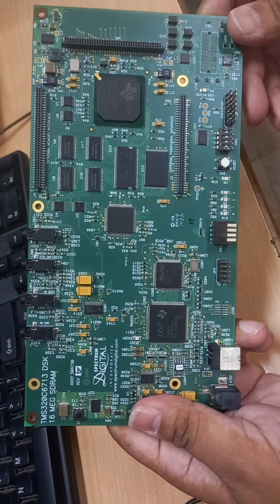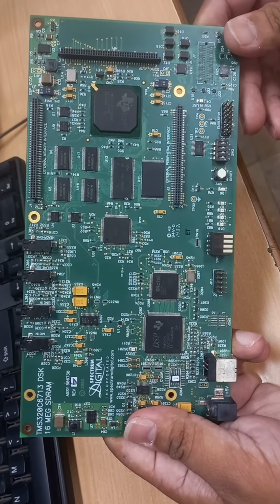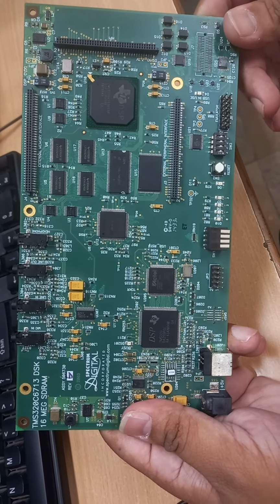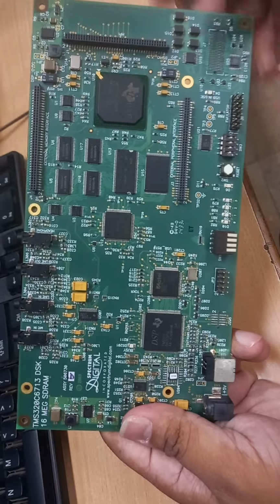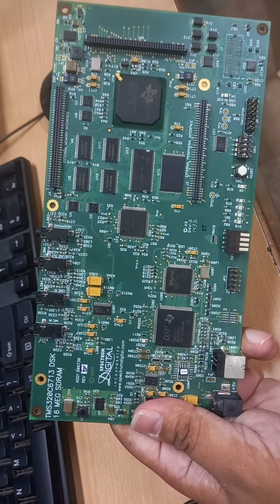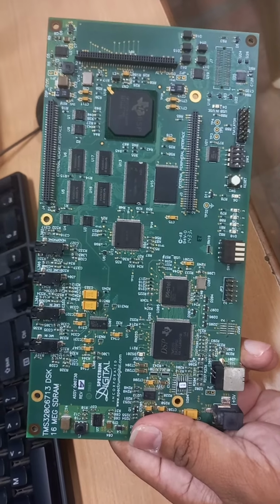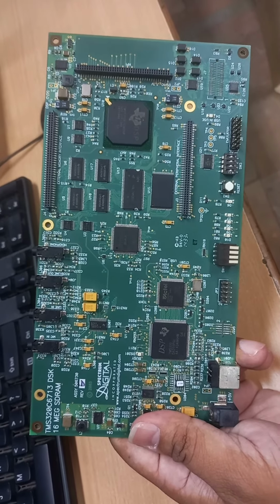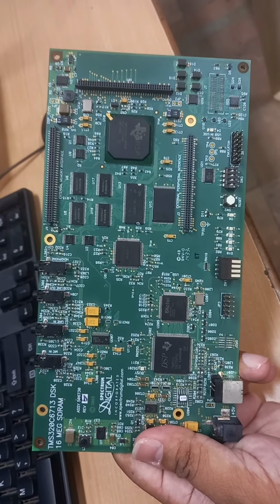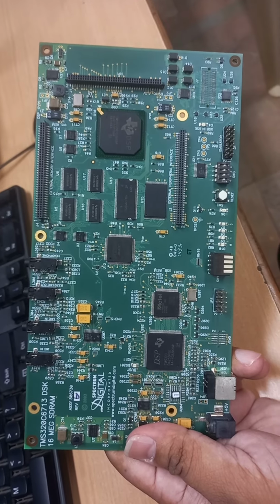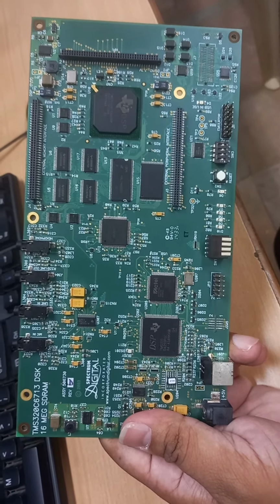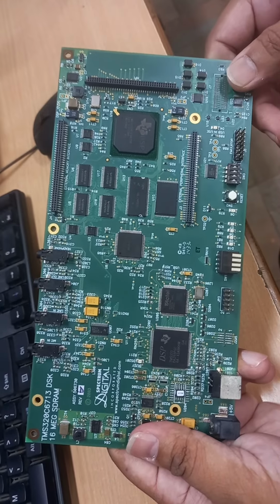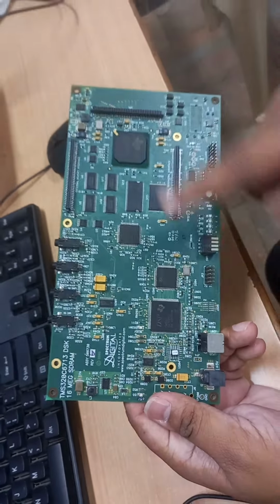The one real-time program we have is the implementation of the FIR filter, called the real-time FIR program. The difference between non-real-time and real-time programs is that with non-real-time programs, you will view the output on the monitor itself, but connecting the kit is compulsory in both cases. With the real-time programs, you will connect the output of the DSP kit to an external device like a CRO or function generator and view the output there. So these are the main parts of this kit.